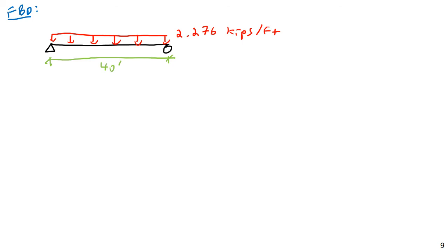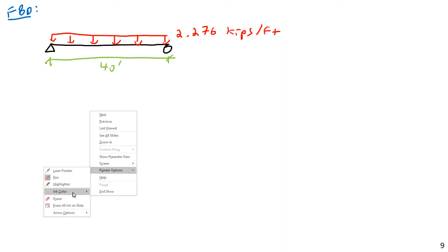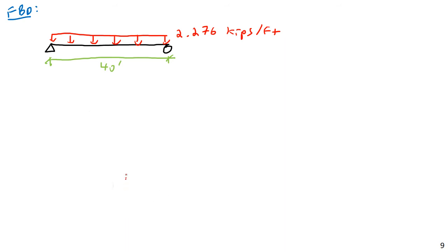Well, the difficulty in that is that you might end up with different load cases that will produce different values for shear, moment, etc. If things were balanced just right, it probably won't happen this way that often. But if things were very unfortunate, you could end up in a situation where your ultimate moment was controlled by one load case and your ultimate shear was controlled by another load case. And if that happened, things would get very complicated very quickly. But we'll probably avoid anything that complex for this class. We have enough material to cram into this class trying to conclude both steel and concrete design in one semester, which is absolutely crazy, but we'll make do.